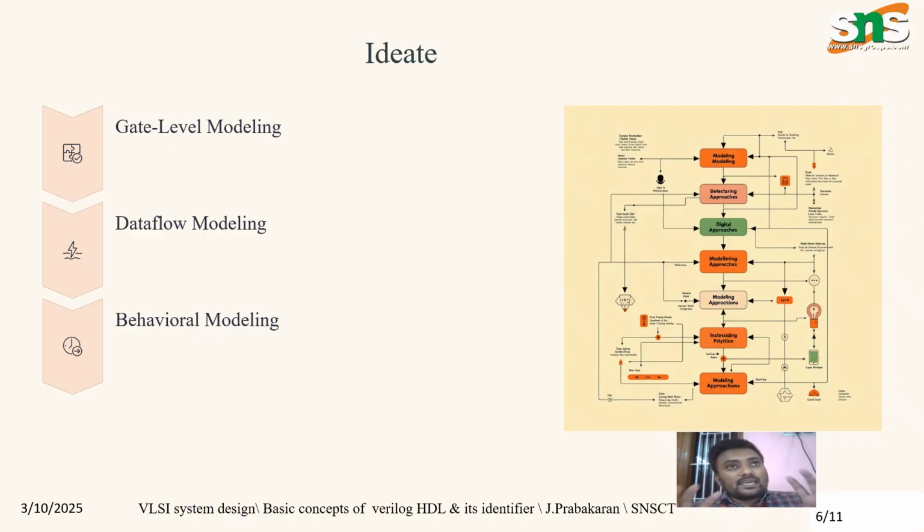This is gate level modeling, followed by data flow modeling, which describes signal flow using continuous assignment, describing how data moves through the system using continuous assignment and Boolean expressions for concurrent operation.